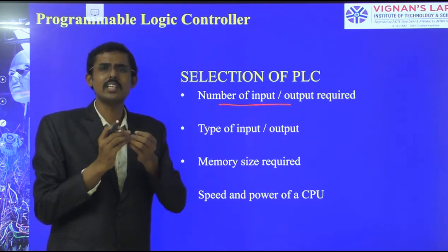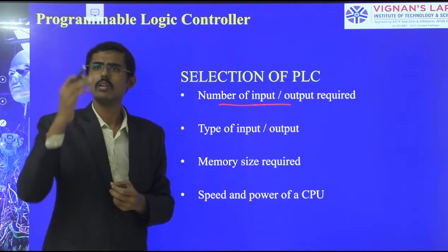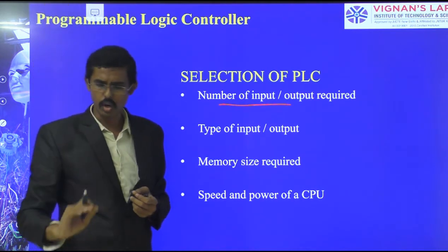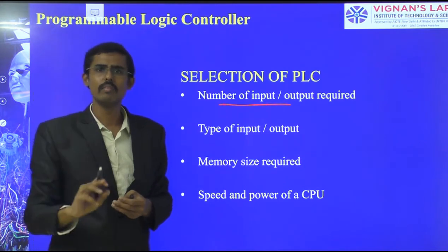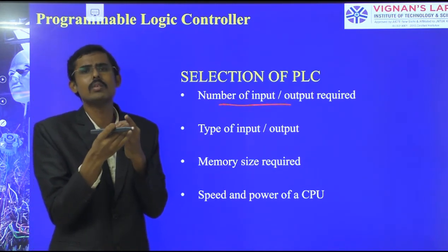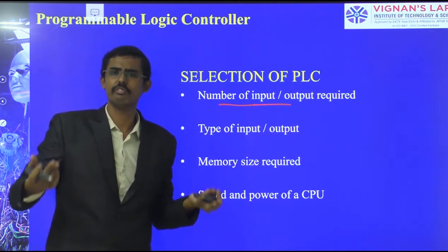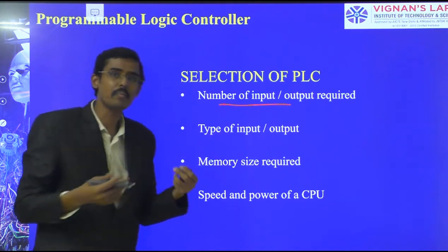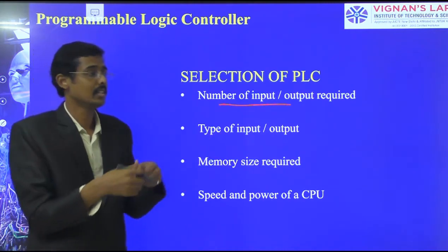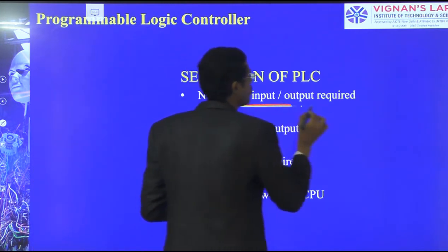I want to operate a single water level management on the tank at home. So it should turn on, it should turn off. High level, low level, so it has to be sensitive. We can take a low level at one sensor and a high level at one sensor. Two inputs are there, and the output motor should switch on and off. So in such cases, depending upon the inputs and outputs and what execution is there, I select the number of inputs and outputs.